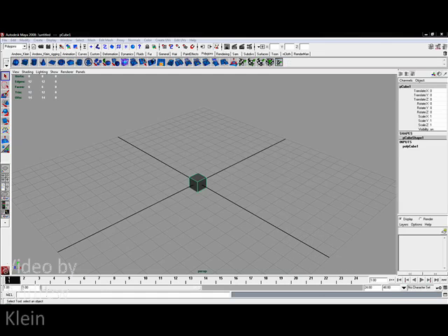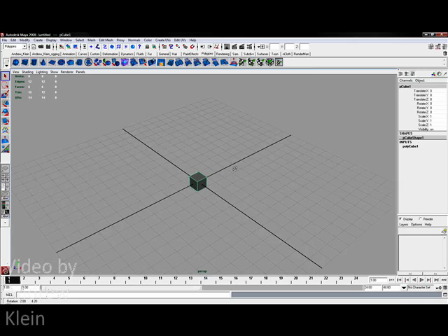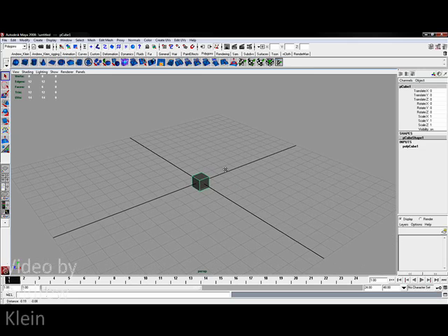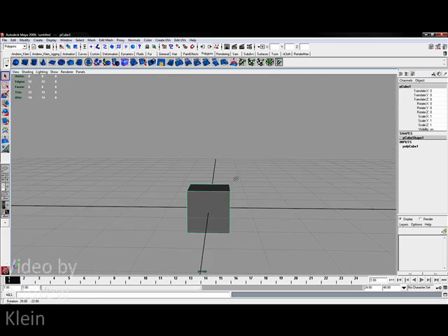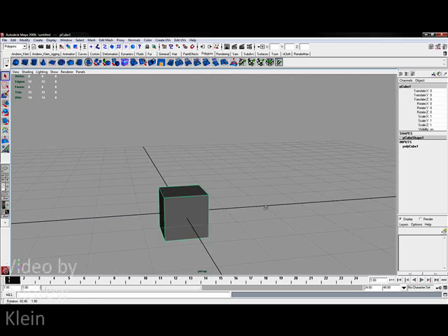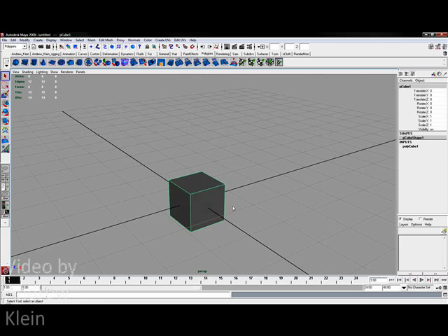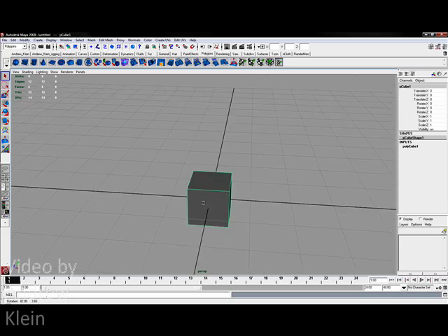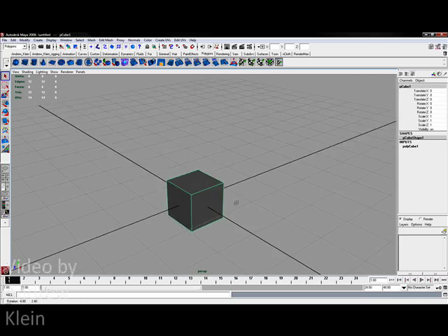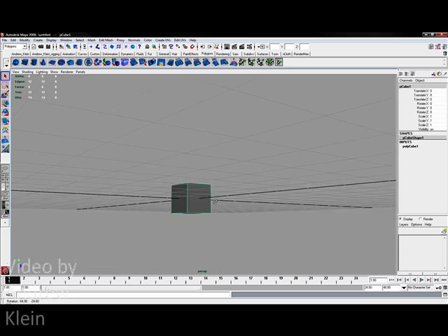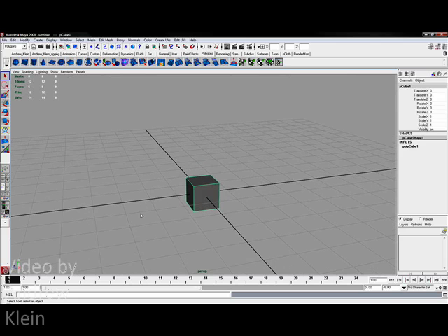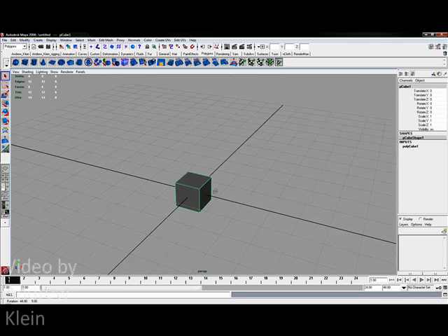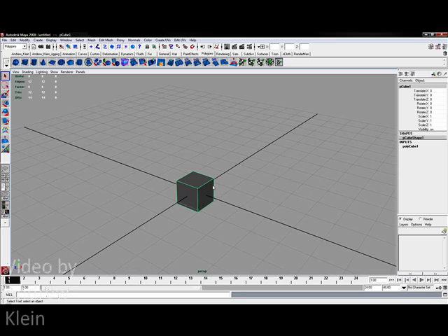Now, by now, you're no doubt aware that there are several different types of 3D geometry. There is the NURB surface, which is inherently curvilinear, and there's also the polygon surface, which is inherently straight-edged, as you'll see here. A third additional type of 3D geometry, called the subdivisional surface, is sort of a hybrid between the two, and something that probably you'll examine later on. Now, we're going to start off with the most simple type of 3D geometry, which is a cube and a polygon model. Very easy to understand and makes it very easy to work with for this task.